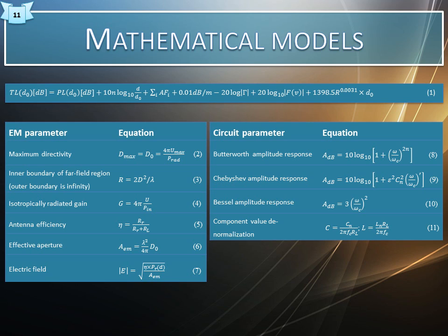The first equation is constructed to represent the path losses at millimeter wave frequency, specifically around the 57 to 64 GHz unlicensed band, where constant values are given assuming operation within this band. The equation accounts for free space losses, reflection and diffraction losses, attenuation through material, and rain rate attenuation.